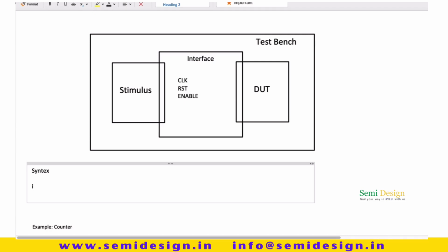First, write interface, then the name of the interface, parentheses, and here the port list. The port list means the ports which we will initiate or declare in the testbench. Similarly, as we end a module with endmodule, here also we close the interface with endinterface.